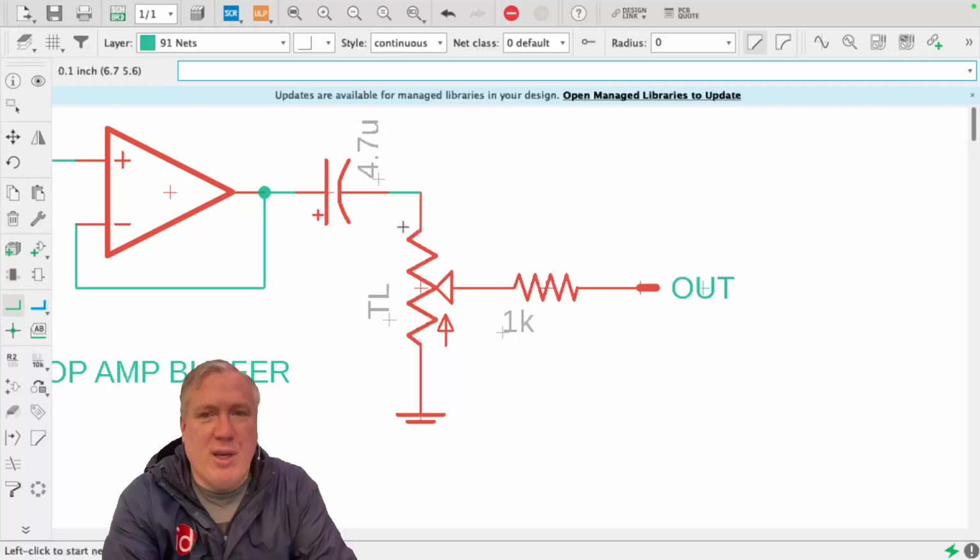By going here, if I turn the potentiometer down towards 0, I get no signal. And if I turn it all the way up, I get the full volume, the loudest possible signal. I've created a volume knob. This is called a passive attenuator. It's a very simple circuit, just one part. But we need to choose its value.